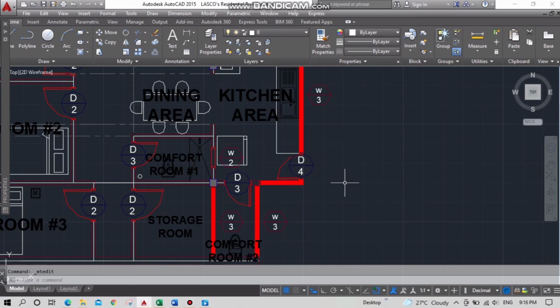And then, for the Section 808, window openings. Every room intended for any use not provided with artificial ventilation system, as herein specified in this code, shall be provided with a window or windows with a total free area of openings equal to at least 10% of the floor area of room, and such window shall open directly to court, yard, public street or alley, or open water courses. So, lahat ng windows namin dito is pumasa siya sa National Building Code.